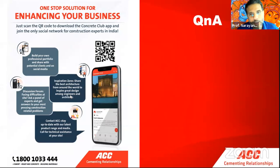Water curing compound. I do not know the type of curing compounds available, but if you are using a curing compound, that is fine. But ultra high performance concretes are very, very sensitive to autogenous shrinkage. So be very careful. And we always recommend that at least for the first 48 hours, you use water curing.